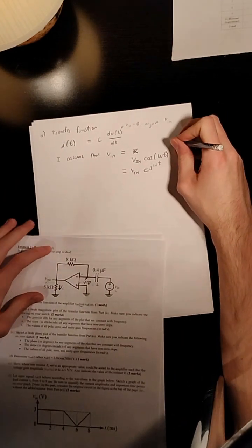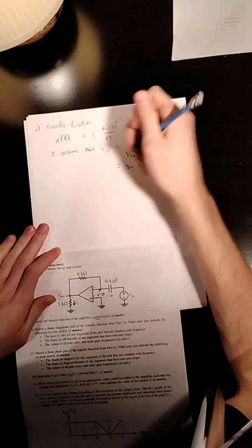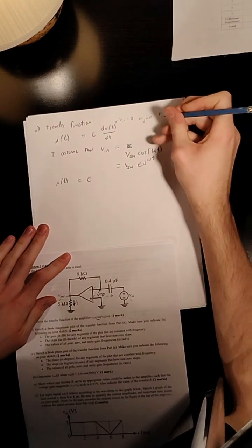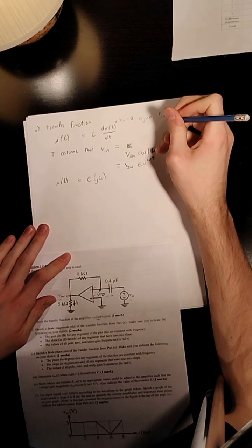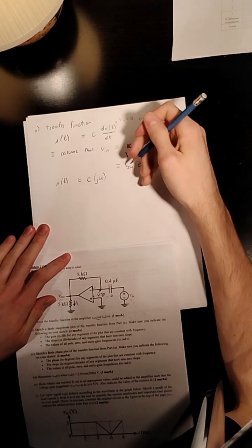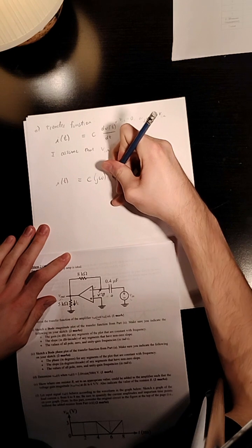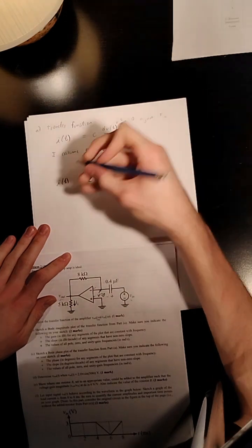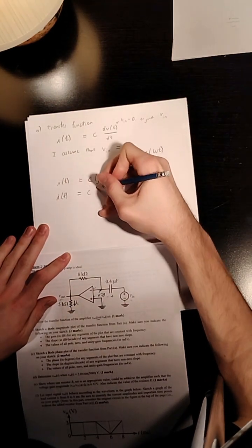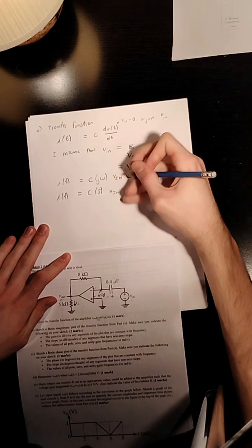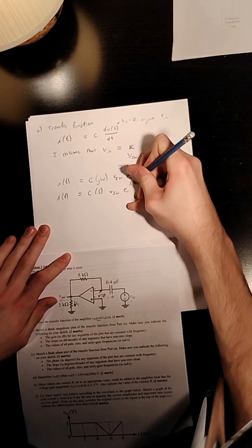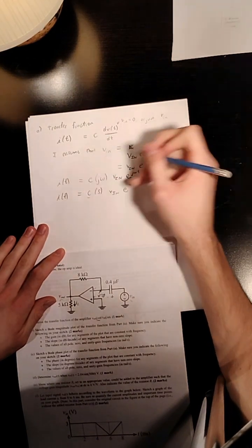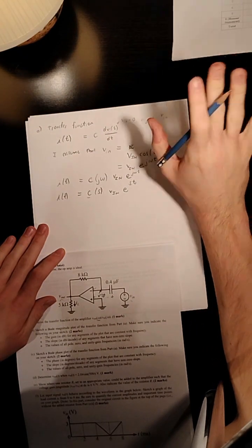Okay, so what we can do from there is take the derivative. So we get I of t is equal to C times j omega. Oh, right, I want to represent that as S. I'll do that in the next step. Times V in times e to the j omega t. And then I of t is equal to C times S times V in times e to the power of st. Okay, we have C. I'll just leave it like that for now, but keep in mind that that's a given